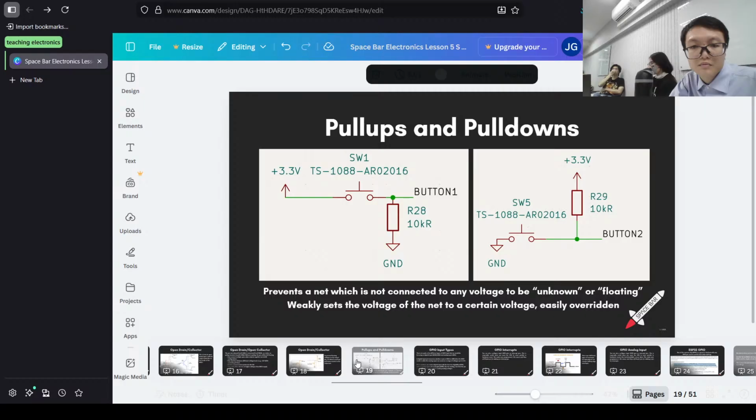Okay. So there are different types of GPIO inputs. Now we are sensing data from the real world. A traditional digital input just measures whether a pin is high or low, so 0 or 3.3 volts. This is read, for example, in Arduino with digitalRead.